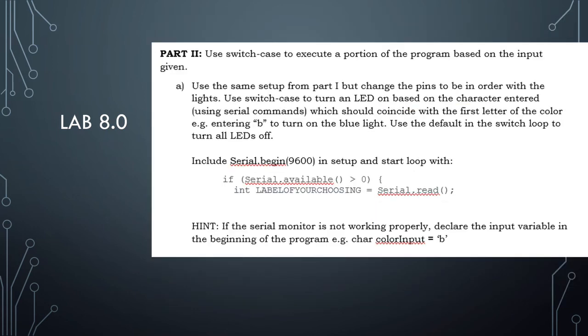The second part of your lab, we're going to focus on using switch case. So for this part of the lab, to keep things simple, I do tell you to put your LEDs in order this time. So you just need to go ahead and switch which pins everything's connected to and put them in subsequent order. You could really use an array still if you feel like a challenge, but essentially it'll be much easier if you connect to them in order.